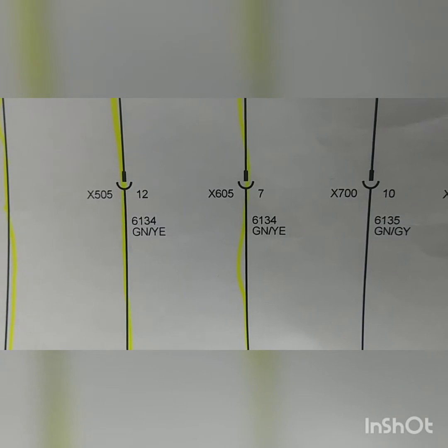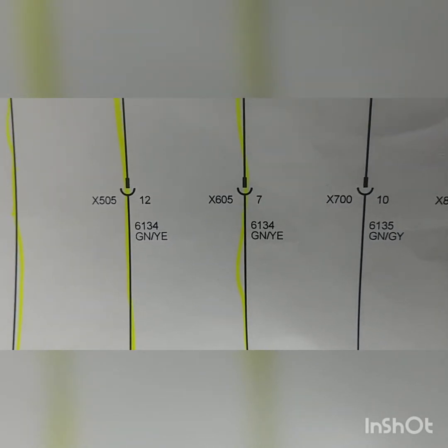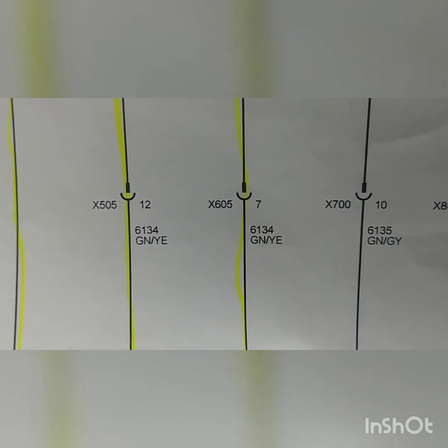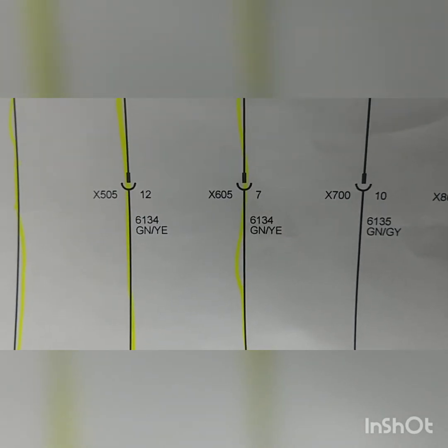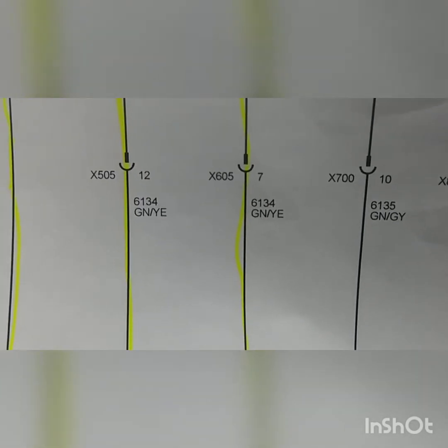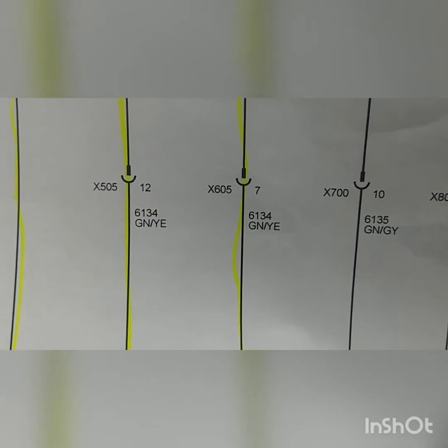and I took apart the connector again. I inspected it and I didn't see anything wrong with it. It was just a factory defect. Probably the pin didn't push in 100%, and when I recycled the connector, we got that line to come back alive.